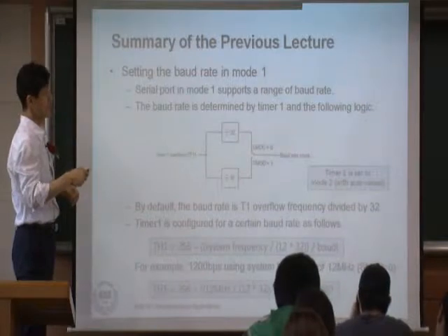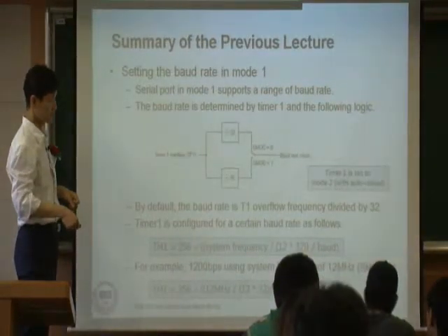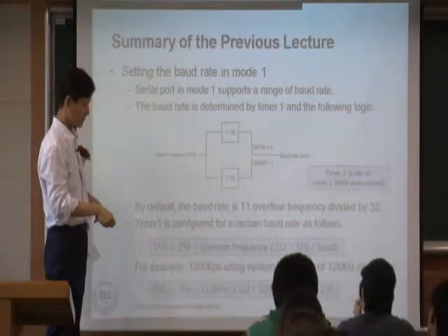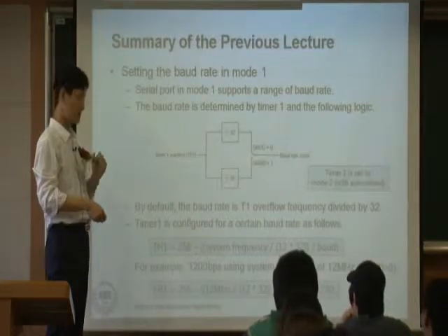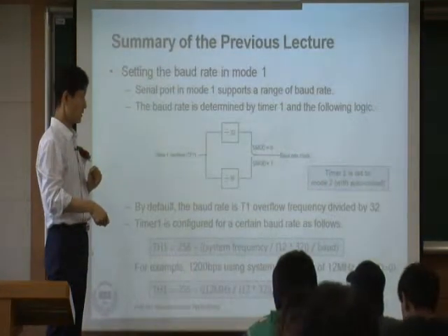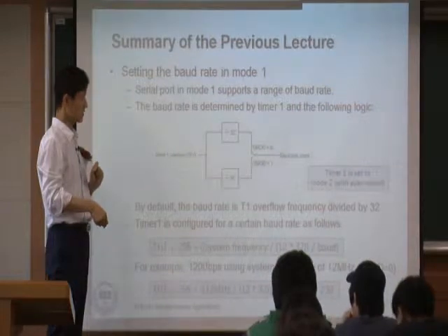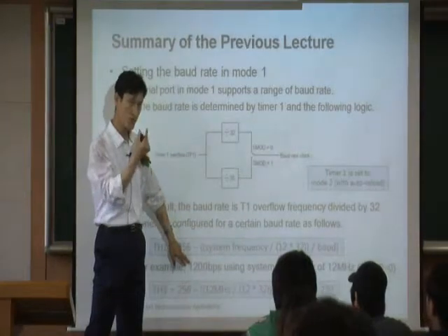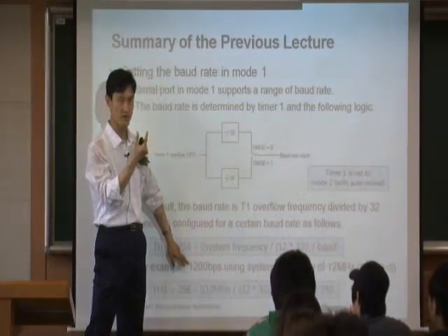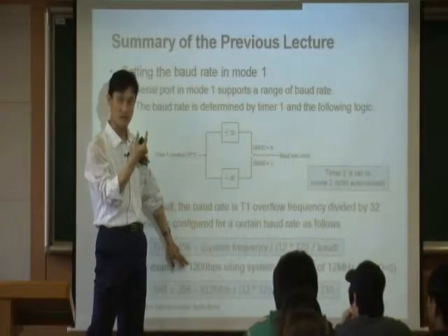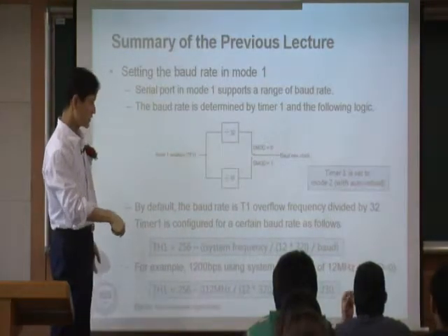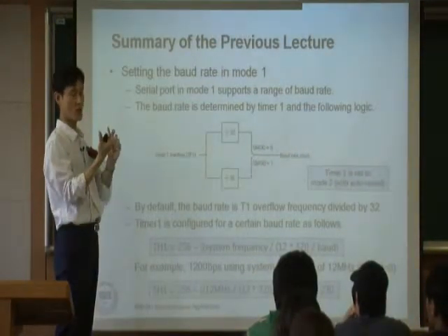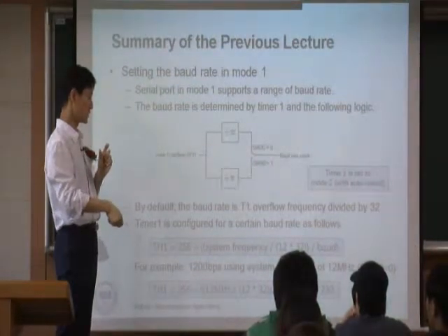Based on the baud rate, such as 1200 bps, the transmitter is transmitting 1200 bits per second, and the receiver is expecting this speed. Now the problem is, this means that one bit duration is almost 800 microseconds. 1,000 bps would mean one bit is 1 millisecond, but it's 1200 bps.